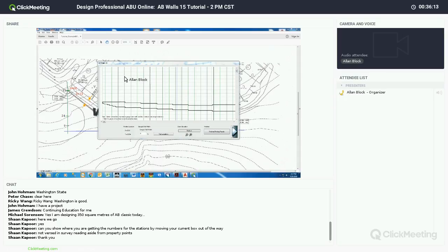All right. So there's a couple of ways or decision options to use on how to cut your wall into panels. You can either go based on above wall conditions, so you have a slope on one section, you have a surcharge on another, or you have absolutely nothing above your wall. You can make that decision based off of the location in your wall. So if it's at 30 feet, you would find the green line that is close to it by using the X and Y coordinate system below. You can notice here it's going in the lineal length of your wall, so you can determine that way if you want to make your cut at a certain lineal footage.